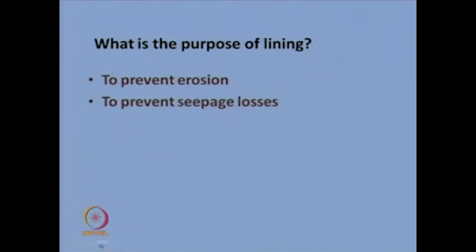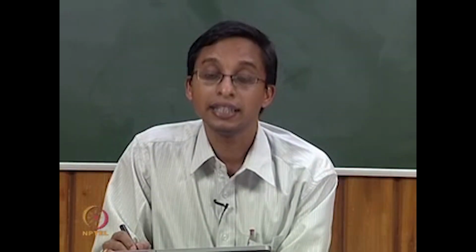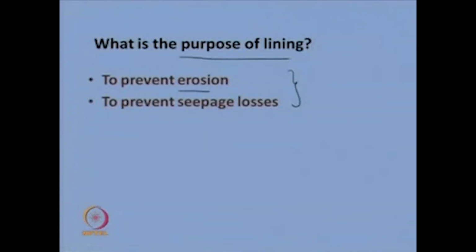As I asked you earlier, what is the purpose of lining? Now, in between this lecture, why do I need to pose you this question? Because, to reiterate in front of you, as this is the design of non-erodible channels, you have to line the channels, and this lining is done to prevent erosion of the bed as well as the sides, and to prevent the seepage of water into the channels.